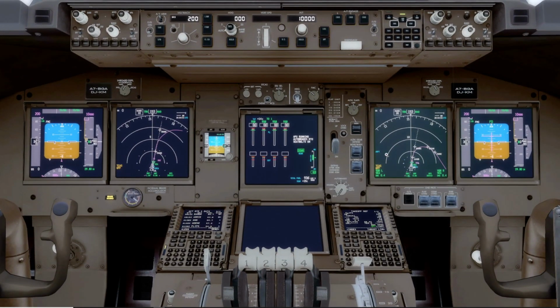For the captain, he'll come across here, start with his EFIS control panel. He'll do the same thing. Go to ADF or VOR, or one of each to at least check it. ADF, VOR, and then at some point he'll go to VOR, maybe when taxiing out or whatever, but to check it, he might just go ADF, VOR. That's technique. You can do that any way you want to.